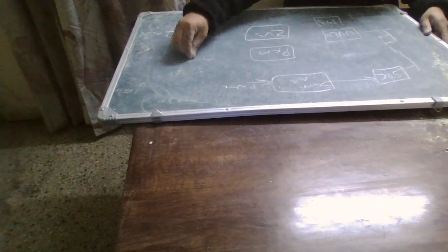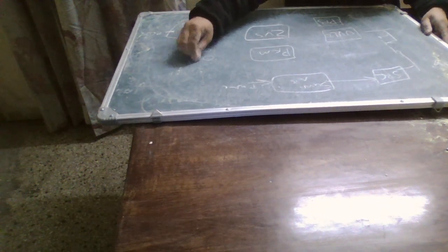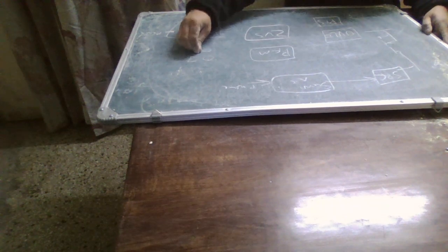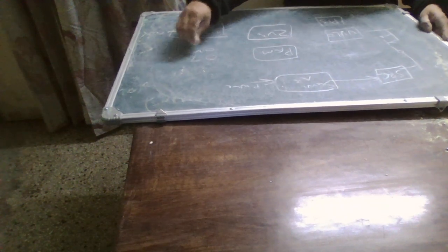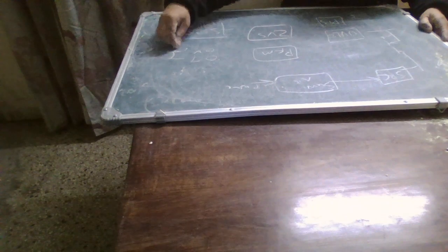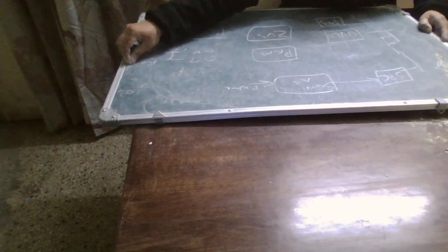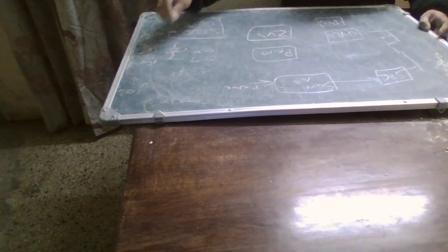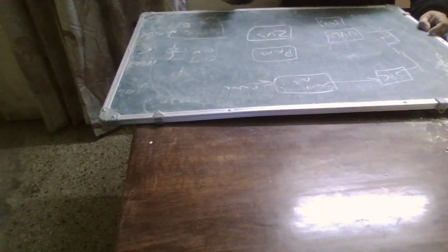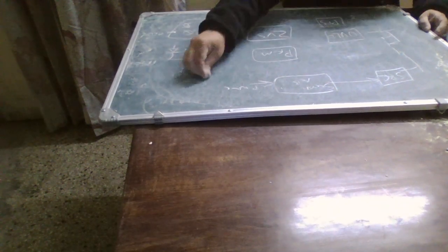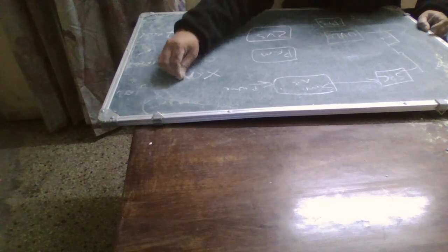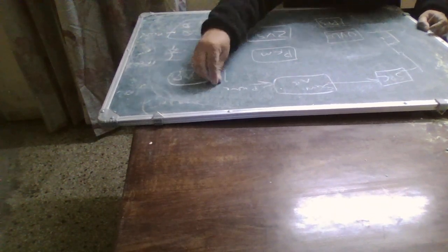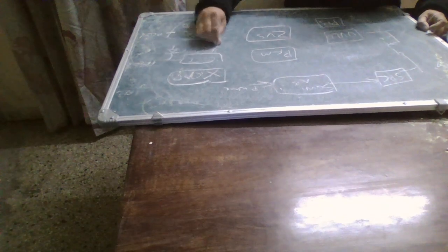And here we have an OT detect, over temperature detection, and over line, over voltage detection. There is a Schottky diode here. It would be the input. The fault pin would be here, and we have an X cap, what I have talked of. This is an X cap. This is an OT block. This is an OV block, or we can have one block here.